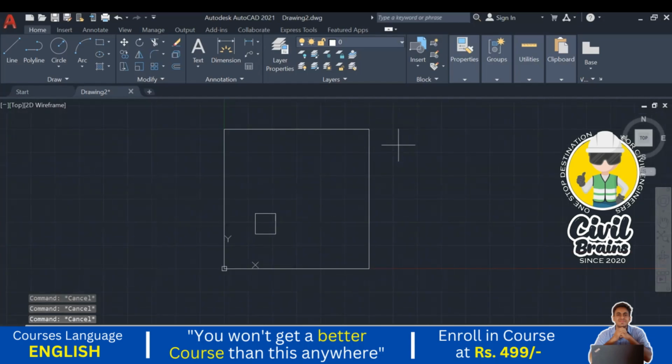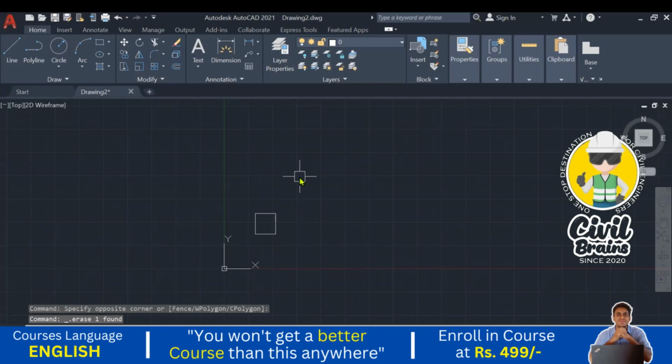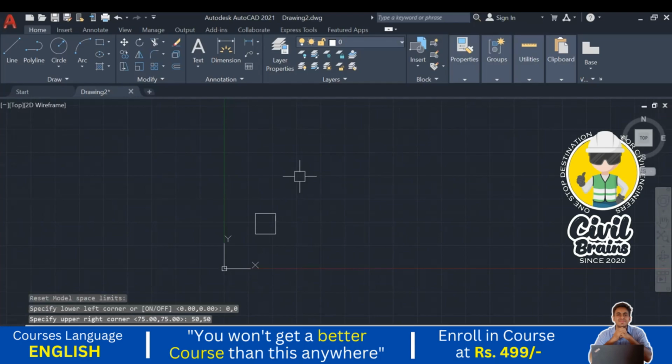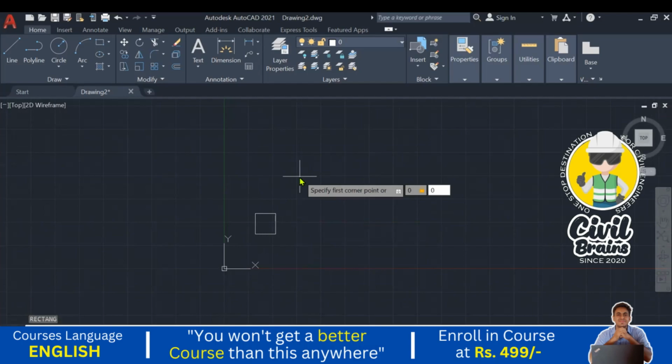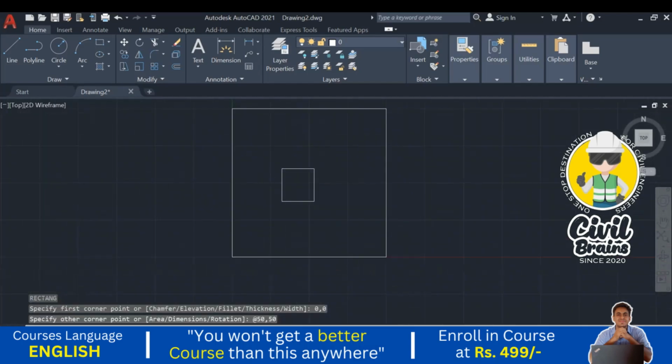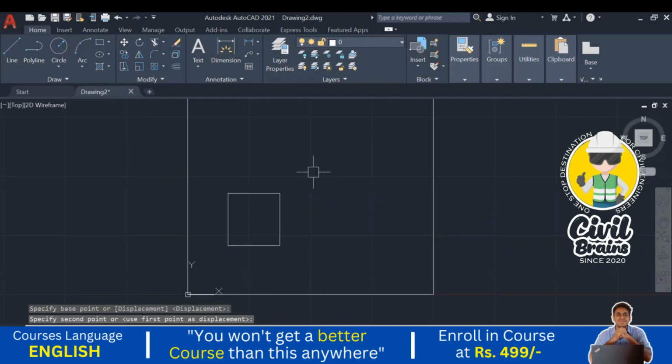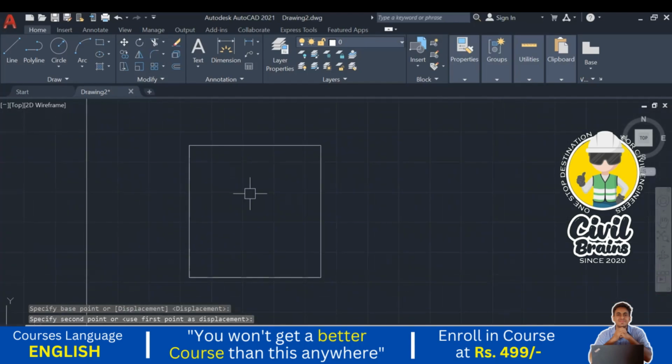I just delete this one. I just put one more time limits 0, 0, 50, 50 I will take now because it is looking very higher side. So 50 by 50 I'm just taking. REC, enter. 0, 0, enter. 50, 50, okay. So now the limits are okay. So I just put here in the lower side, I just put the plan over here. This is our outer dimensions.